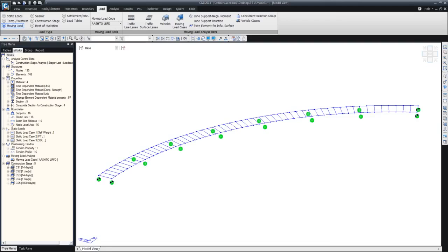Another question that is coming in: by the 28 days girder, do you mean the girder has already been cured for 28 days when it is being erected? Yes, that's true. The girder has already been cured for 28 days and then brought to the field.